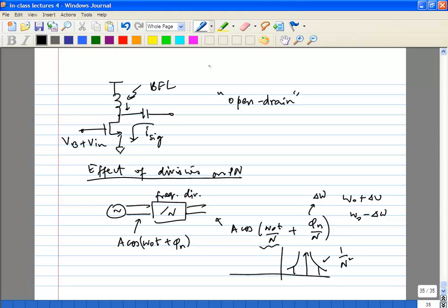Doesn't matter. If it is a resistor, we can consider it as... Okay. It's like taking only every N-th edge. Yes, sure. Well, if you look at most dividers, they don't exactly work that way, right? Typically they're counters, so you have to worry about noise on every edge. You don't just discard N edges. What you're talking about is pulse swallowing, right? These dividers will not be like that. They'll be synchronous counters, so you have to worry about noise from every edge. Okay.